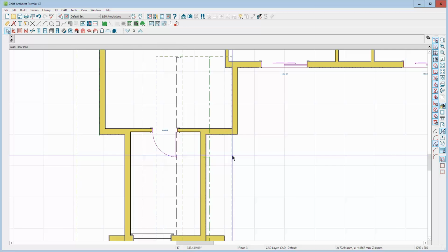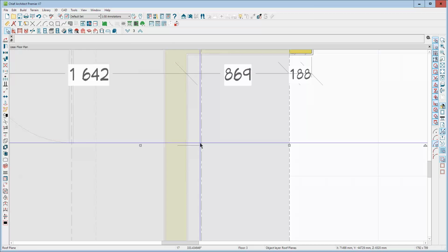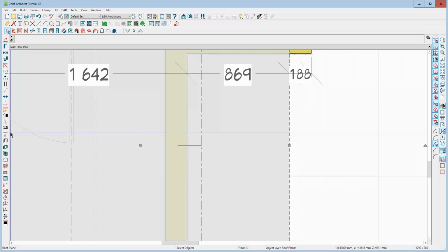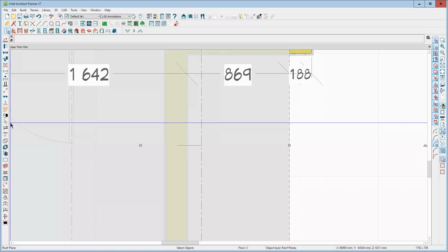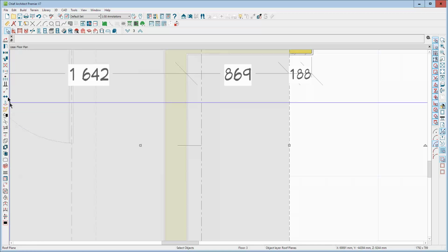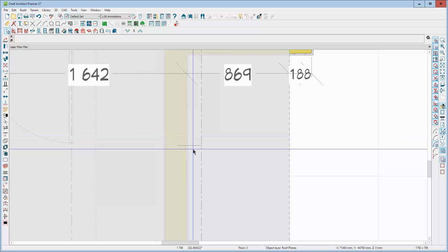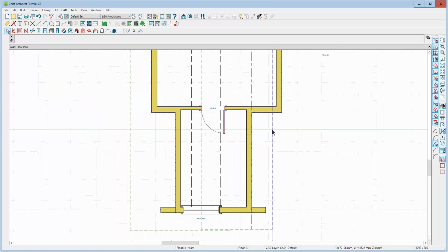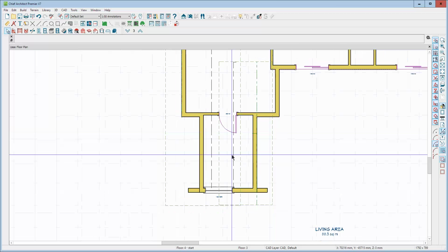And this one here, I'm going to move this baseline from where it is to over a wall, because the baselines transfer the virtual load of the roof to the wall, and that's how they should be designed most of the time. I say most of the time because there are exceptions. Okay, I got that done.